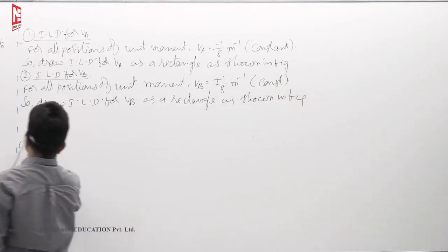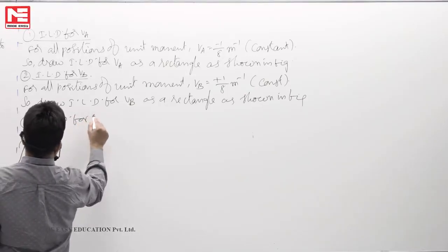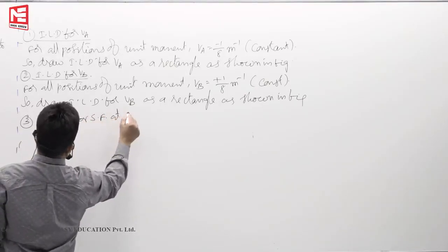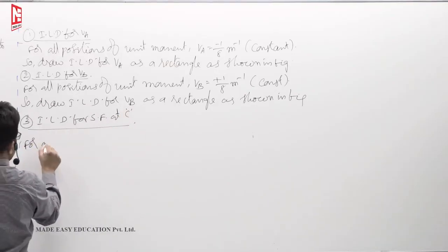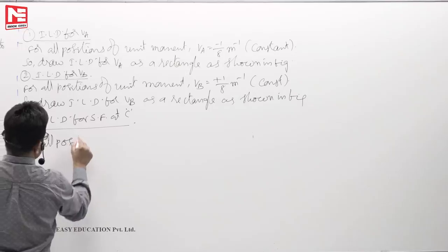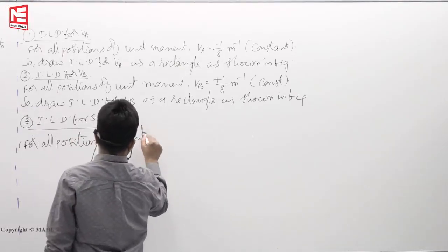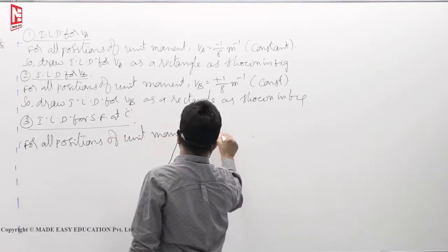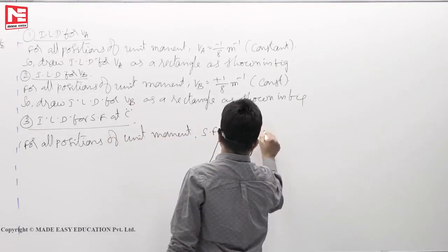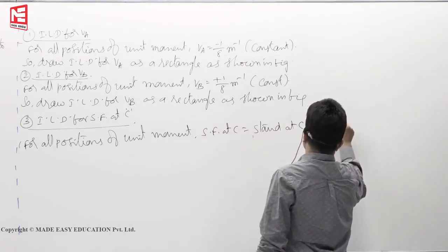Next, ILD for shear force at C. Again, for all positions of unit moment, shear force at C means what? Stand at C and look right.